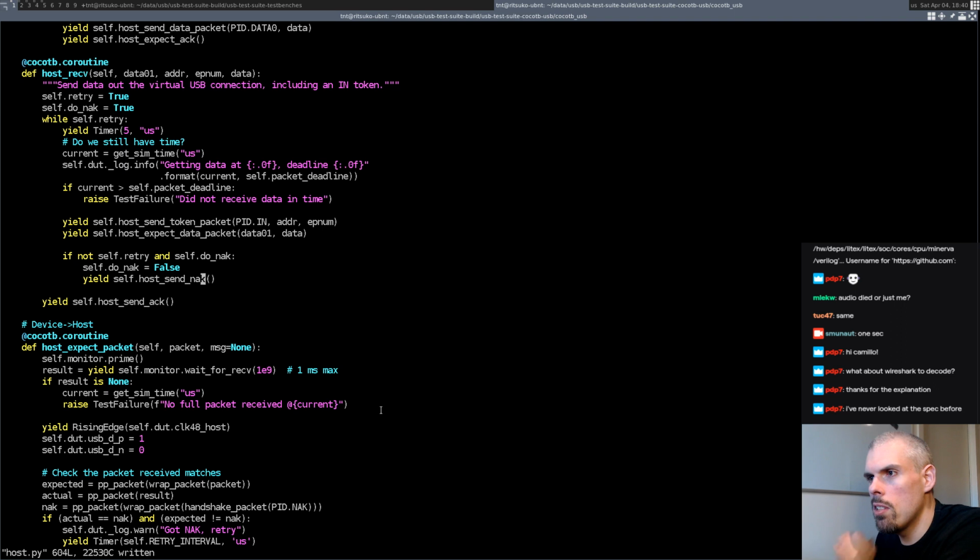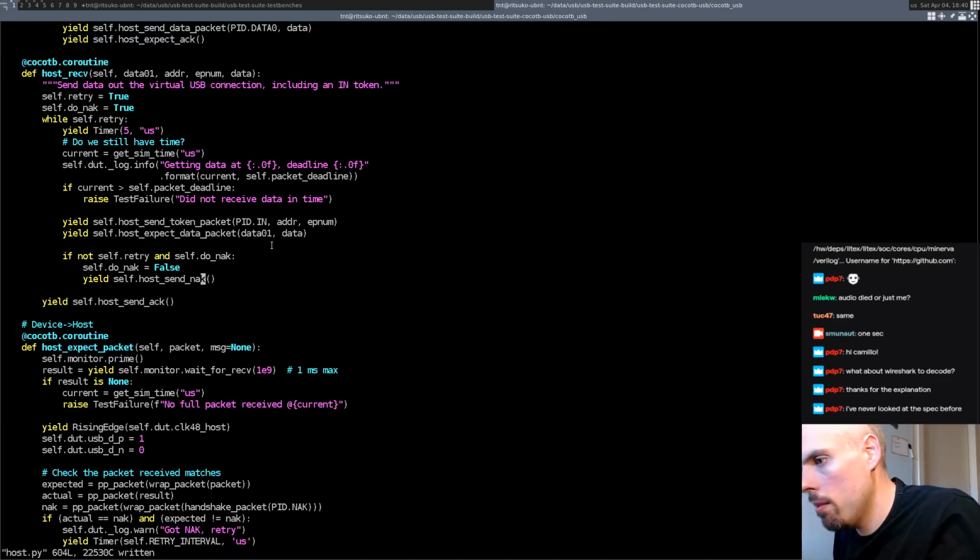Okay, so that should be it. When we do a receive, every time there is an IN transfer, we're just going to force an error by NAKing the transfer and forcing the device to send the same data again. Let's try to simulate that.